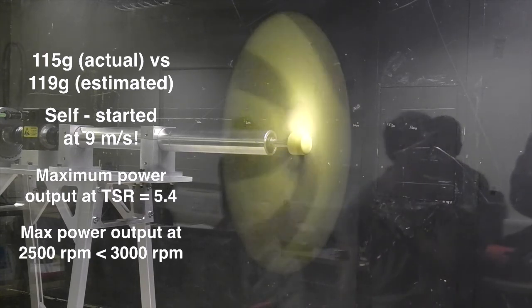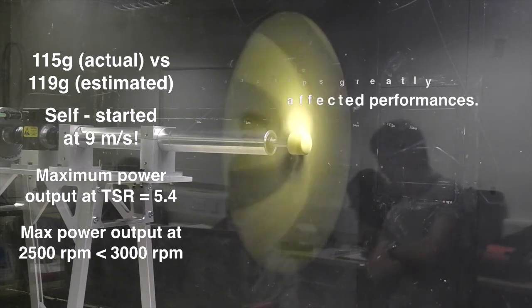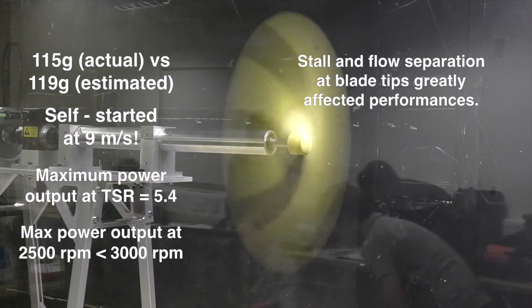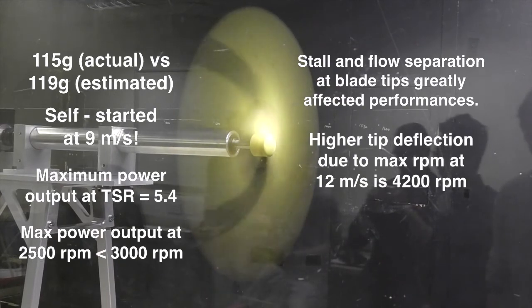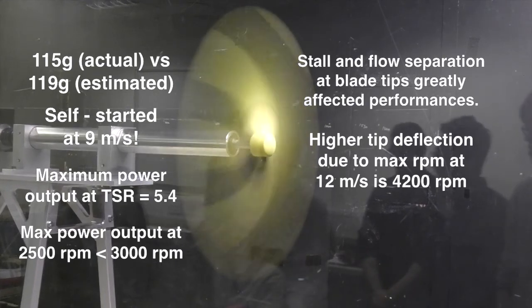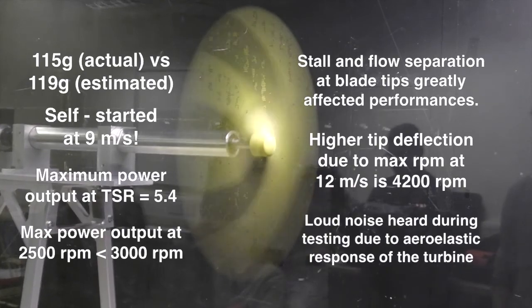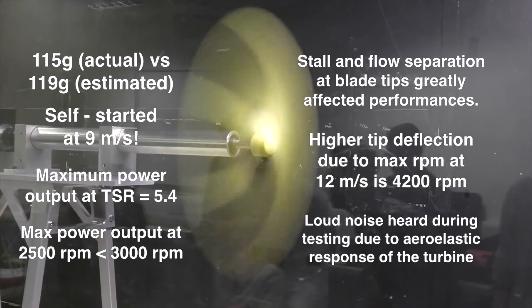A considerable tip deflection can be seen when being run at higher wind speeds. Because of the occurrence of stall behavior and flow separation near the tips, the performance of our wind turbine was affected significantly. We believe that the tip deflection was far greater than we had anticipated because of the higher RPMs, 4,200, where we estimated a tip deflection of 2 mm for an RPM of 3,000. During testing, we also heard a short, loud interference that we believe to be due to aeroelastic response of the blades. Thankfully, this caused no issues, and we continued to test at wind speeds beyond this point.